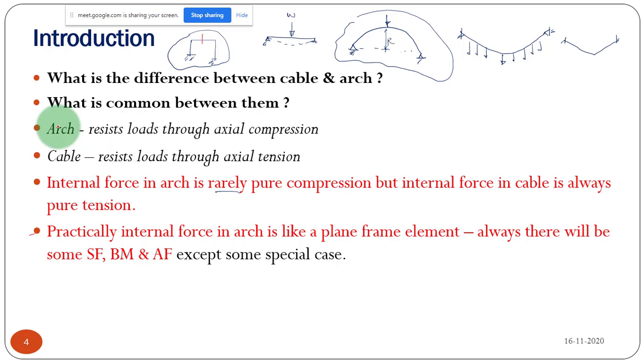Because here we have discussed arches, we can also make an arch that is going to experience only compressive force. That is also possible. That is why I have written here except some special cases. Except in some special cases, in arches also there will be three internal force components. We can treat it like a plane frame structure only. So there will be moment, shear force, and axial forces in general. But except some special cases, I think we will discuss this.